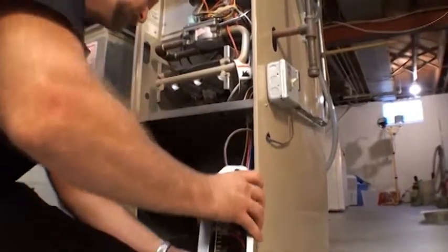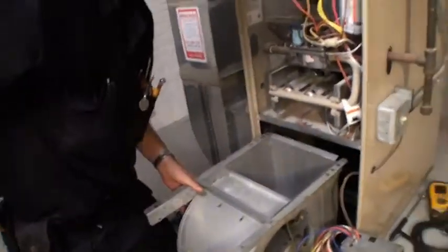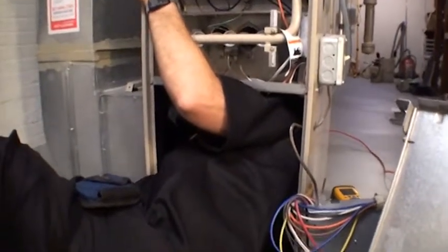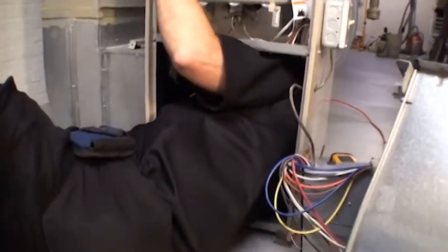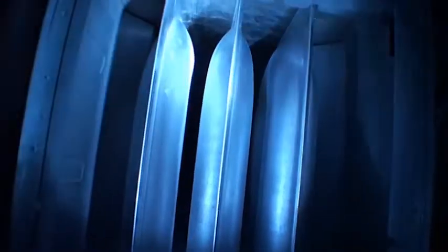Proceed with the clean and tune by pulling the blower assembly out. Check the heat exchanger for cracks and the A coil for airflow. You need to put your head in the furnace blower cabinet and look up at the heat exchanger and A coil. If a crack is discovered, you must stop all work and call Community Action. If you see any debris, you will need to clean the coils.